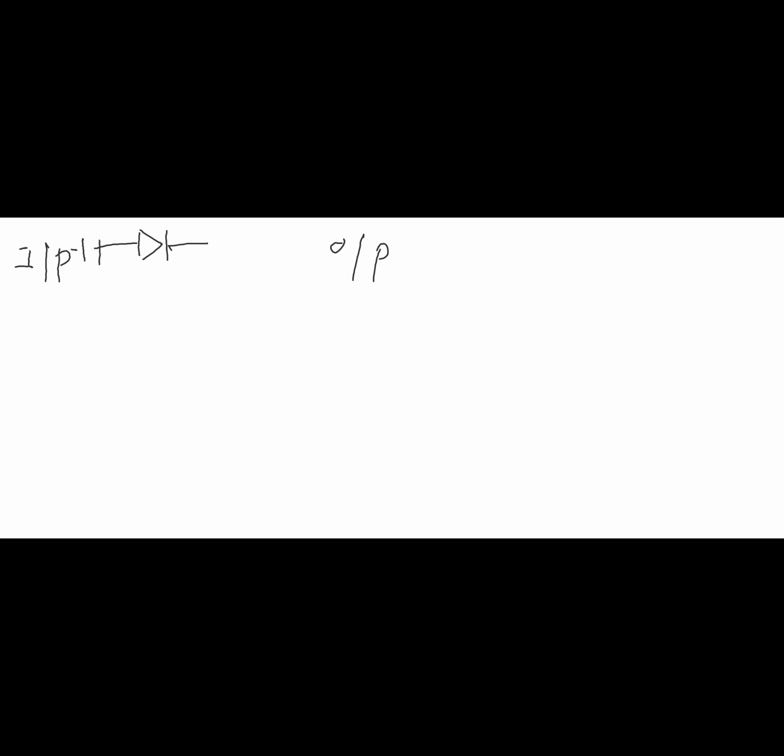So capacitor, that is one thing, on the input side and on the output side. For the AC signal, the capacitor will act as a short circuit. So when you apply an input signal through the capacitor, it will reach the diode, and finally the output capacitor will act as a short circuit and you will collect the output. But now how to deal with the DC? For that, one inductor here, like this, and this is taken as a reference point, and one inductor here.